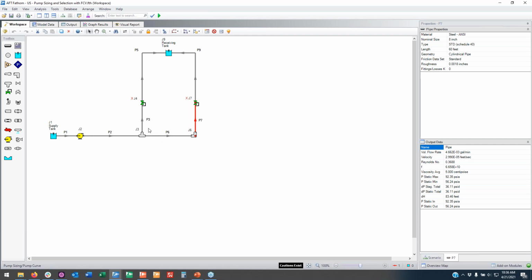And if we actually had flow moving through both of these, well, we wouldn't have flow. It would be stagnant because we can't overcome that pressure differential. So Fathom actually will solve the math and force all of our flow through this pipe leg with lower losses, because when it's moving through that one pipe leg, we can see we actually get flow. And then on this other pipe leg, we can't overcome the yield stress, and so we see a stagnant region.